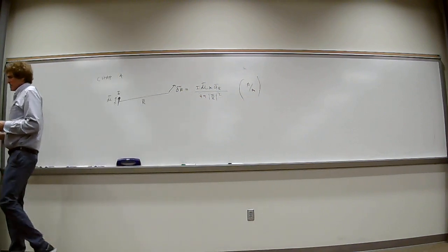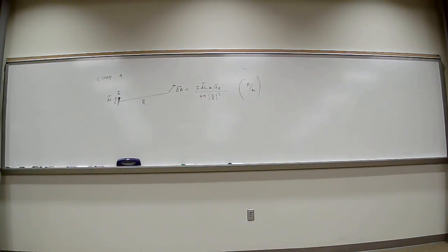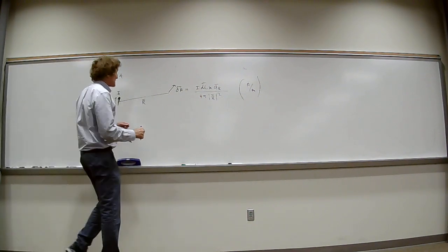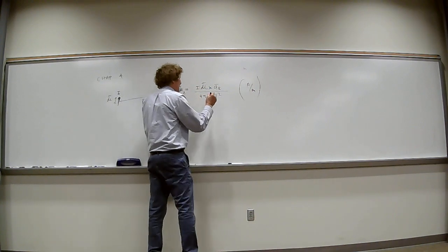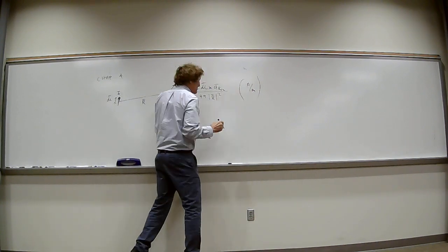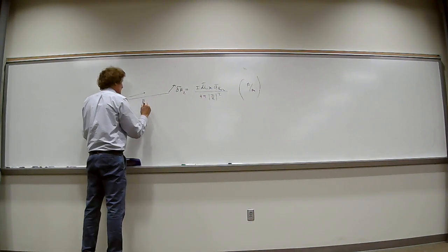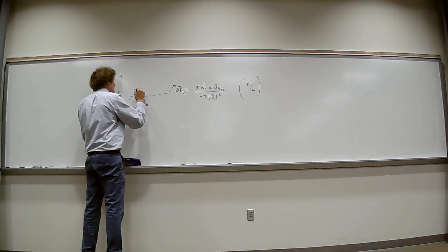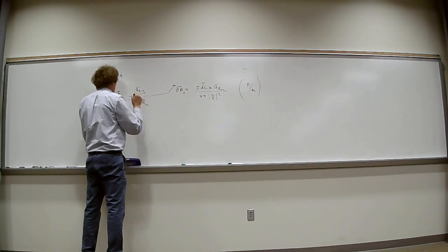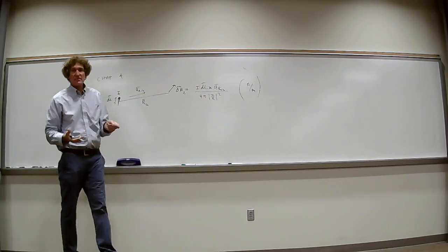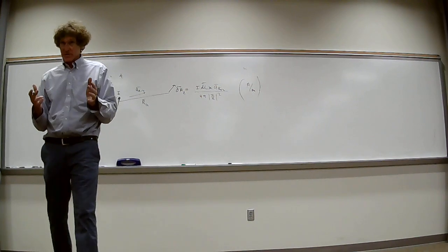And in his book, he shows you this in equation 4.4, but he uses aR12, and then he calls this H2, and he likes aR12. Let me just cut to the chase here. When he talks about this, aR12 is a unit vector that points from the source to the point of observation of the H field. That's the only thing it means. Y'all with me, class?